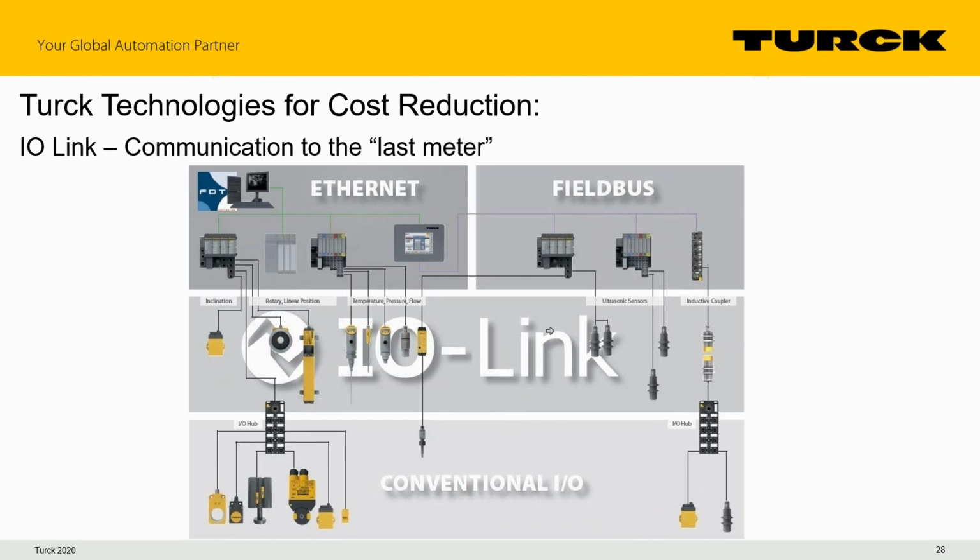We also have some process instrumentation. So if we have a process instrument that fails, normally when we have a process instrument, it requires somebody to know what was that instrument I took out spanned to, what was it the PLC spanned to, and I've got to set the instrument up and make sure it matches before I can get the process going again.